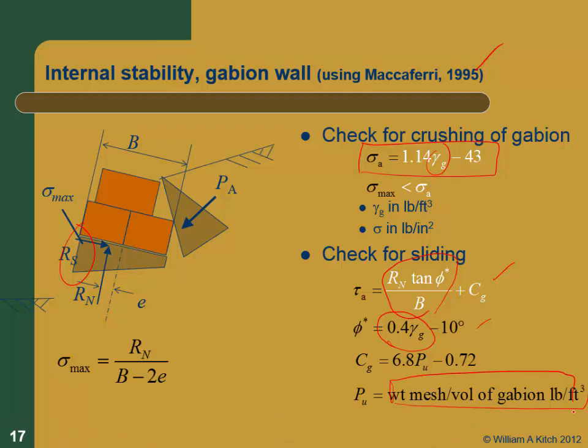It's how much of the gabion material is in the basket. So you have both denser meshes and thicker wire. The way you can get more material in there is either by having a thicker material that makes up the basket for the gabion, or you can have the holes in the chicken wire closer together, or you can have thicker wires. Does that make sense?